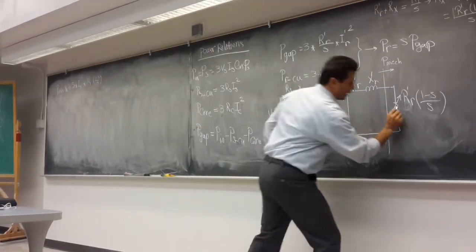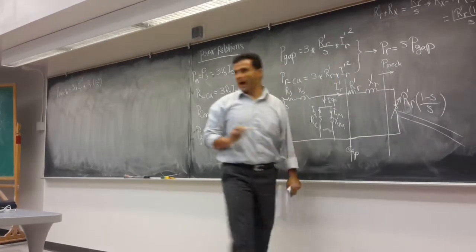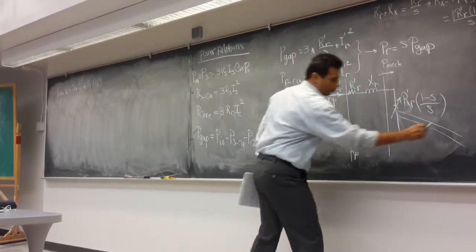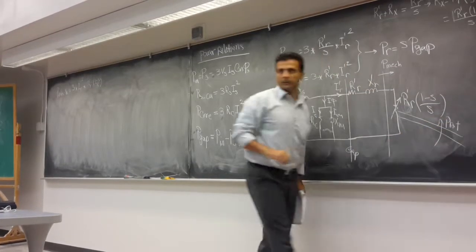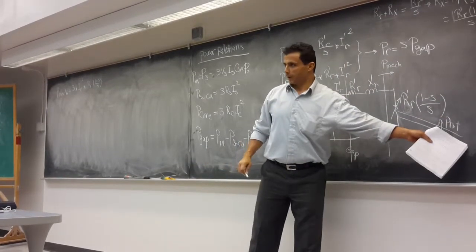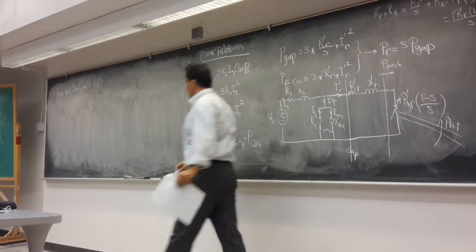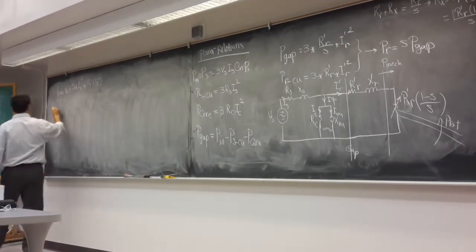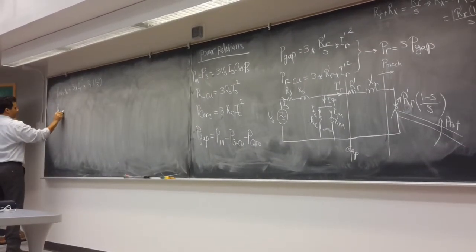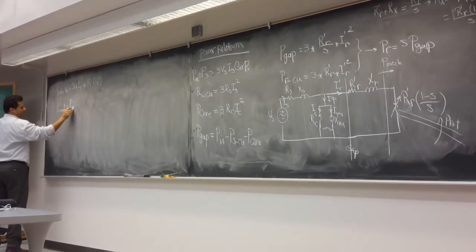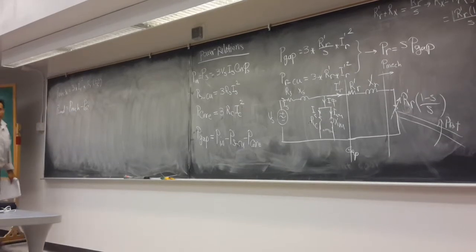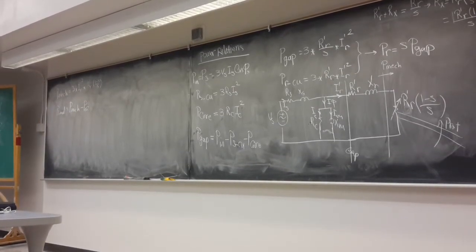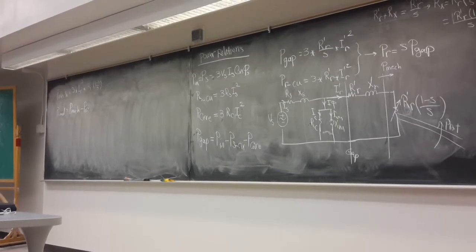This is P mechanical, and if you are going to show it here, this is the shaft. Now we have the P rotational. And that's what is going to be P load, right? After that, it's going to be P load. Now P load is going to be P mech minus P rot. Rot is the rotational loss. Rotational loss is because of friction and windage loss, right?